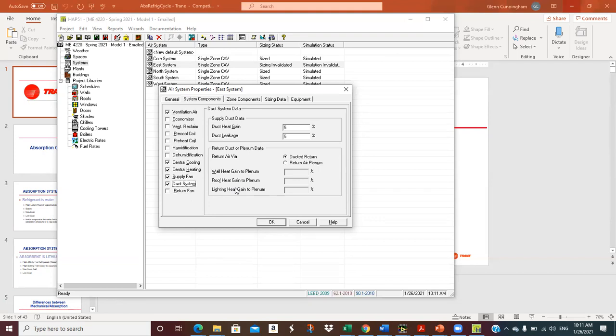Like if it's in a drop ceiling, you could just have the area above the drop ceiling and the fan is just sucking the air back. Say the air handling unit is up there above the drop ceiling and it just has an opening in the back and it's sucking the return air right out of that area above the drop ceiling with no ductwork. So you have the drop ceiling, you have supply registers here and there, and then you just have some return grills.